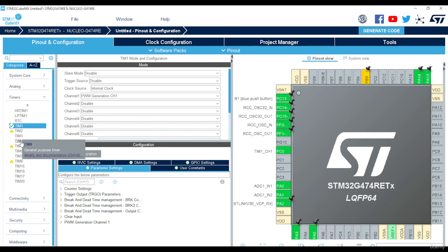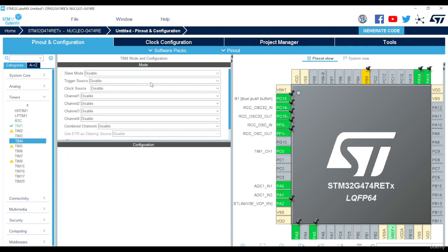And keep in mind that in the previous code, I selected that to generate the digital coefficient, I actually selected the timer interrupt time to be 100 microseconds, which means the frequency is actually 10 kilohertz, which is 1 divided by 100 multiplied by 10 to the power minus 6, which is 100 microseconds. So anyway, I choose timer 4 in this case to implement the timer interrupt.